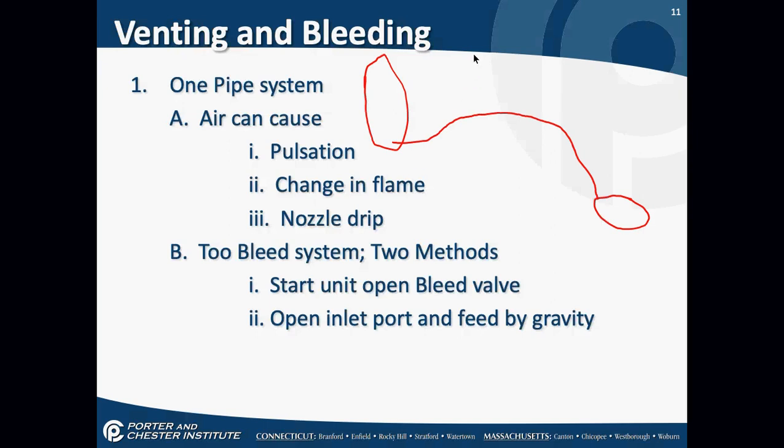Yeah, it has your pipe coming into it, and then it has a little loose metal band or a vinyl band that goes around the pipe, and then the nut goes over that, and it all screws together, and by the pressure on that fitting, it actually clamps the pipe in. Have you seen those before? Yeah. Okay, that's a compression fitting.